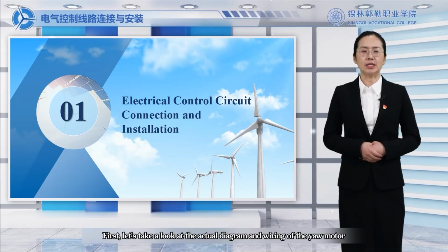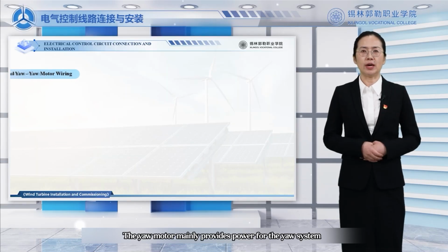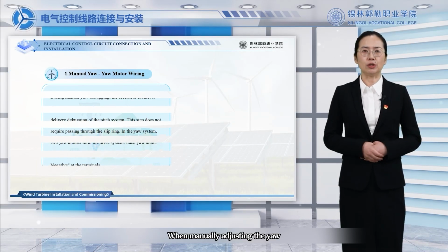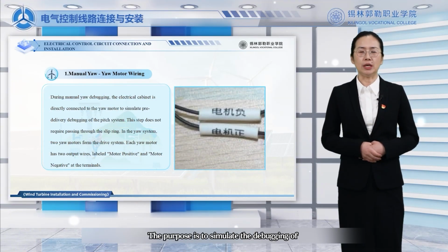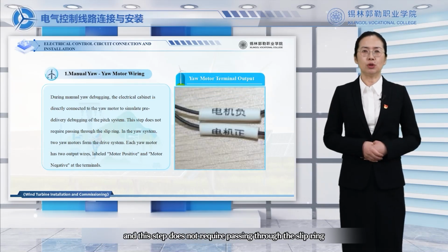First, let's take a look at the actual diagram and wiring of the yaw motor. The yaw motor mainly provides power for the yaw system. When manually adjusting the yaw, jointly connect the electrical cabinet to the yaw motor. The purpose is to simulate the yaw system's operation before leaving the factory, and this step does not require passing through the slip ring.